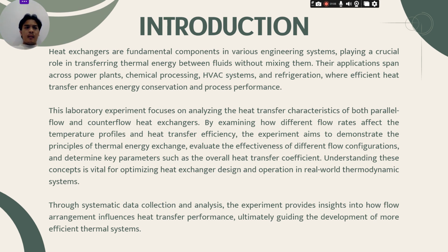This laboratory experiment focuses on analyzing the heat transfer characteristics of both parallel flow and counterflow heat exchangers. By examining how different flow rates affect the temperature profiles and heat transfer efficiency, the experiment aims to demonstrate the principles of thermal energy exchange, evaluate the effectiveness of different flow configurations, and determine key parameters such as the overall heat transfer coefficient.